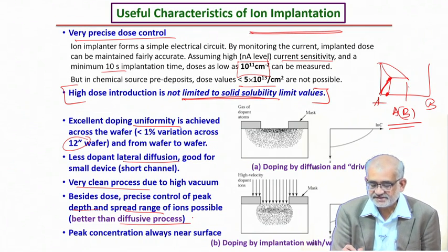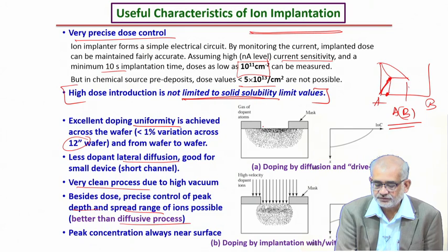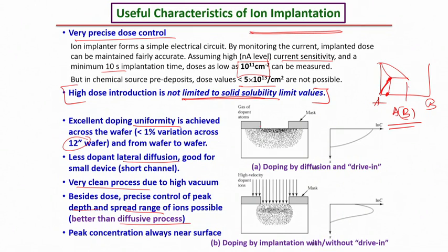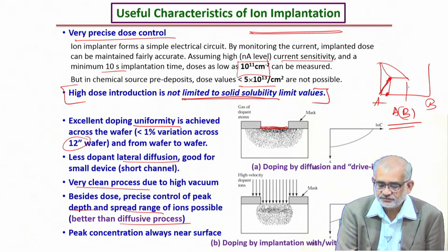Now, what it means is that in a typical thermally activated process, for example, if you electroplate or deposit by vapor deposition this amount of dopant, and even if you have masks here, when you allow diffusion to take place, diffusion occurs certainly down below, but also laterally.